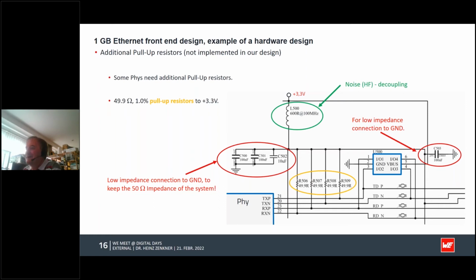And if you forget to block it with capacitors towards the ground here, then you have an impedance, and again the 50 ohm resistor, the whole thing won't be matched. So you must here have a very low inductive connection to the capacitors, to directly connect these capacitors to the reference ground of the balanced signal here. You know, we have 100 ohm balanced, 50 ohm from each line to the ground.